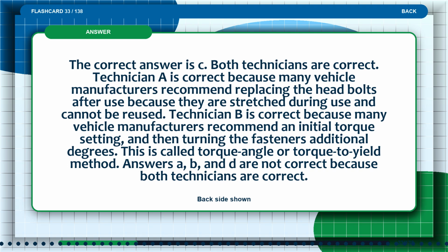The correct answer is C. Both technicians are correct. Technician A is correct because many vehicle manufacturers recommend replacing the head bolts after use because they are stretched during use and cannot be reused. Technician B is correct because many vehicle manufacturers recommend an initial torque setting and then turning the fasteners additional degrees. This is called the torque angle or torque yield method. Answers A, B, and D are not correct because both technicians are correct.